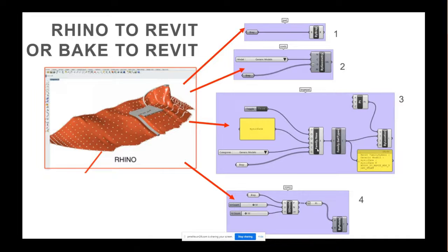The advantage there is that you have the ability to make geometry repeatable in an actual family where the geometry is being controlled by Rhino, not Revit. This is very advantageous, especially when you have very small custom geometry inside of Rhino, like maybe a Corinthian column or maybe some furniture, things like that. Maybe smaller things that you want to make a separate family for. This is very advantageous.